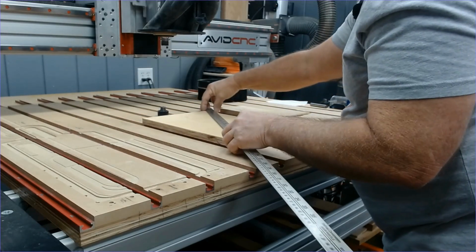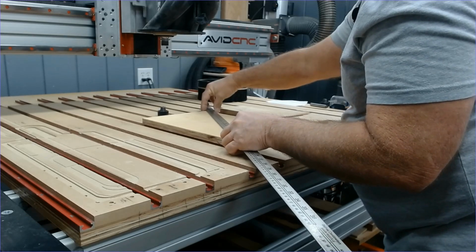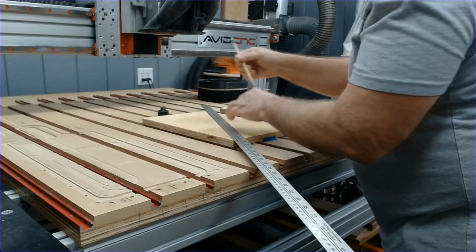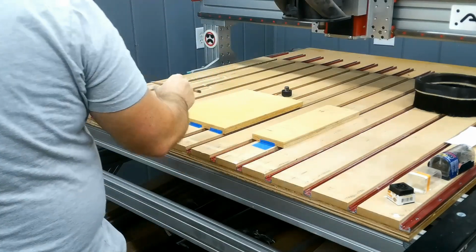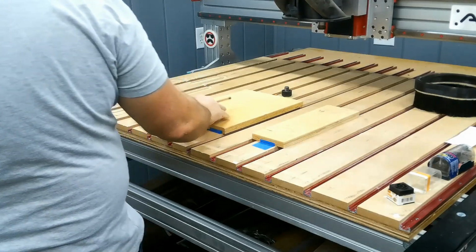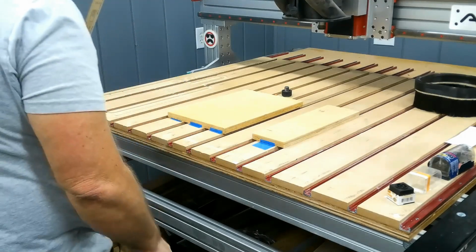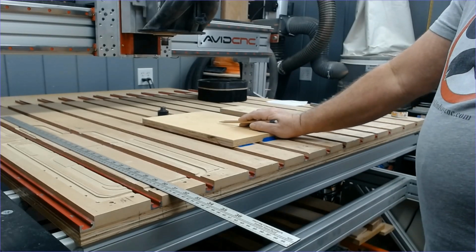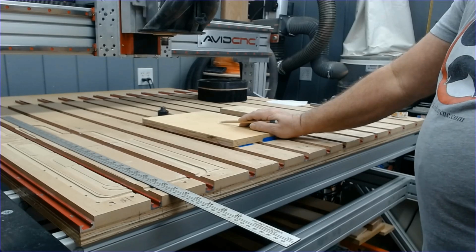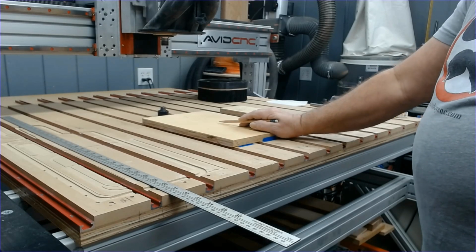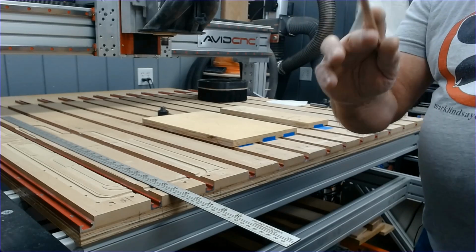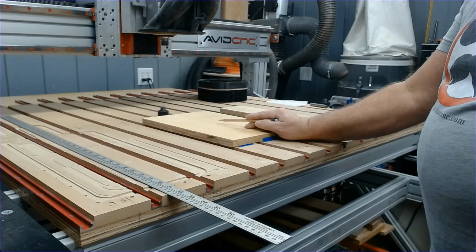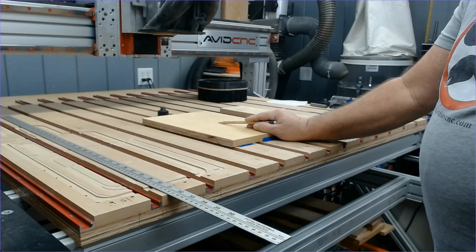Then I'm going to do the same thing coming from the other direction. Just line it up on the corners, hold it down firmly, and strike a line. Now, that mark is much bigger than it needs to be, but hopefully you can see that. This is my XY datum position according to VCarve or Aspire. According to Mach 4 or your controller software, this is XY0.